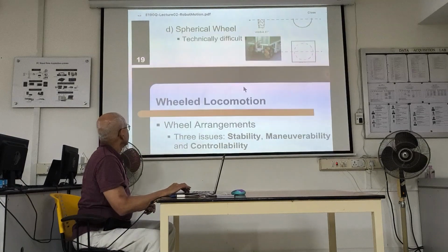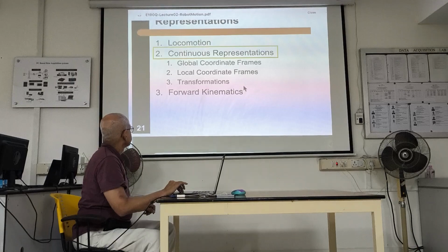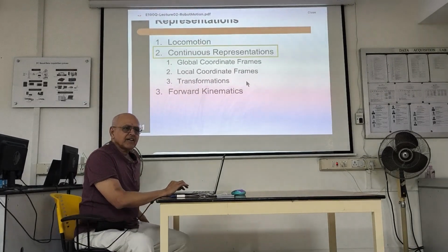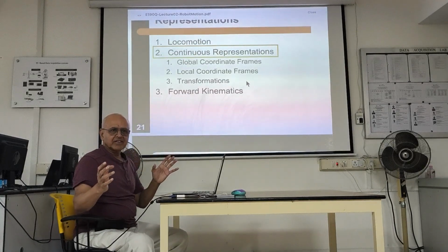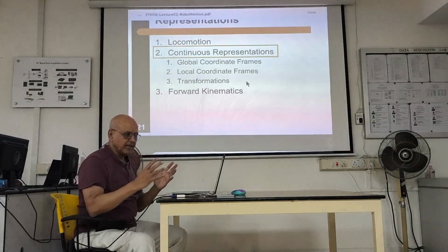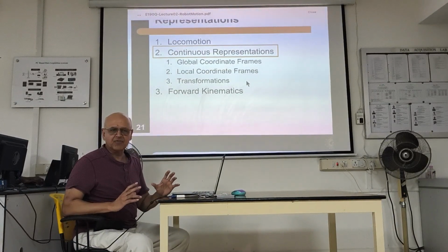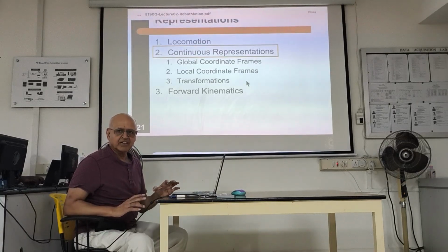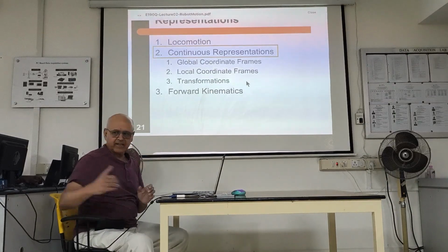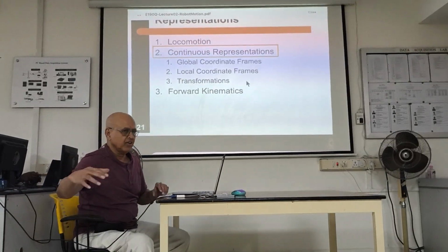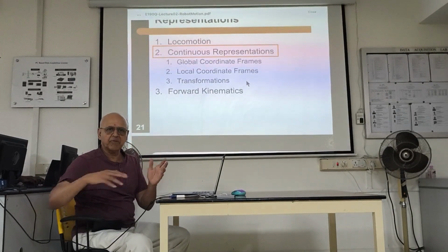So slide 21, I think, is where you begin. So this is the most important aspect of robotics from this point of view. If you want different robots to talk to each other, jointly create maps and so on, there has to be an understanding of what is your axis of reference. I think I already gave you a sense of that, right? If one robot is facing this way and sees something, another robot is looking at it from here, and you're trying to create a map, you have to compensate for the different viewpoint. Otherwise, your map will be all over the place.